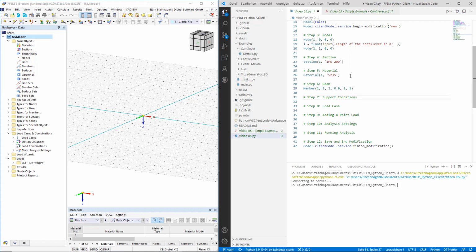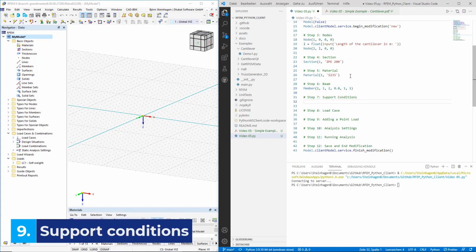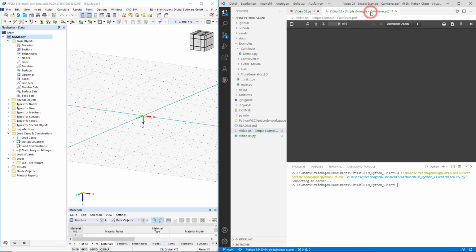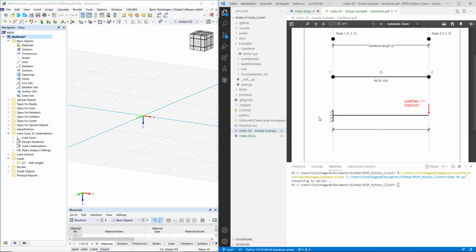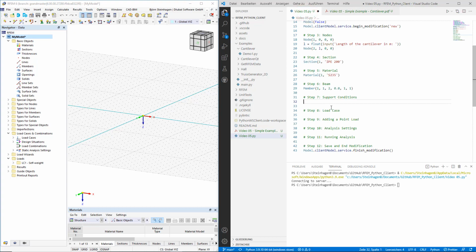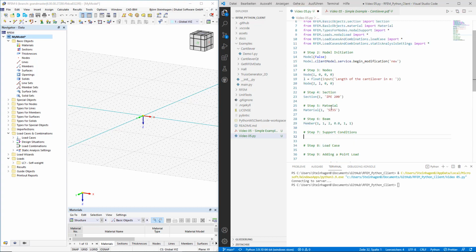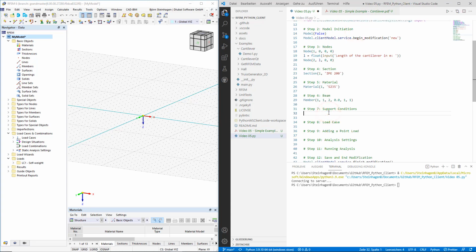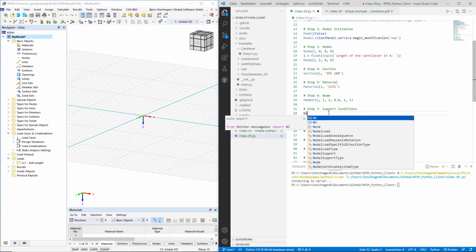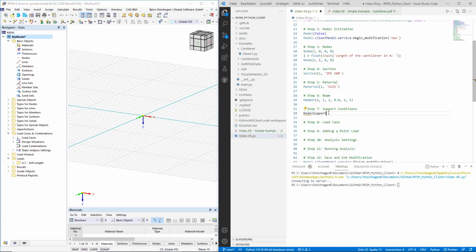With the geometric portion of our problem completely defined, we can define the boundary conditions, i.e. the support for the cantilever. As mentioned, when importing the libraries, this will be done through a nodal support. The nodal support function is regarded as a type for nodes and is found in the RFEM6 library under types for nodes, which is similarly represented in the import sequence. This is the first nodal support. Therefore, like with the previous geometrical entities, it gets the number 1 as the first parameter.